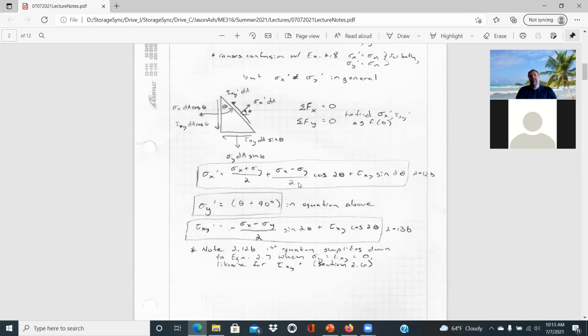This will give you your state of stress along any rotation or orientation. These become important primarily when you're looking at a plane of weakness. Say you have a weld running at a certain angle, you really want to know what the normal and shear stress is along that weld, which would dictate if failure would occur.